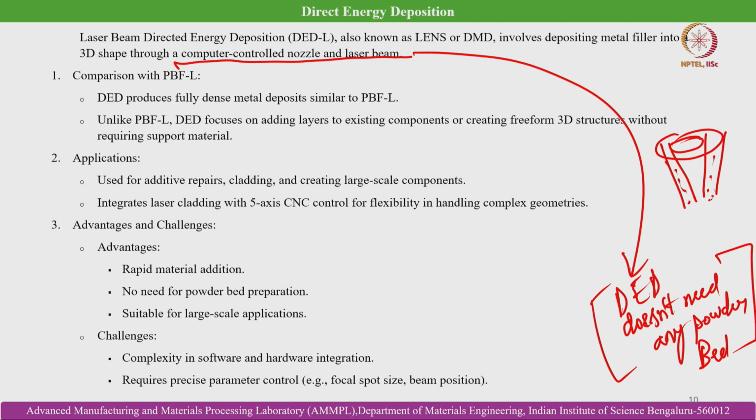So, the powder gets deposited on a substrate plate. Likewise, like I am trying to draw here, the laser beam impinges on the deposited powder and then cures it. Thereby you can get the 3D object made, or the powder build is possible to be made over the substrate plate. Okay, so this is your substrate. Then you can understand that it can significantly reduce the wastage, because of non-requirement of a powder bed.